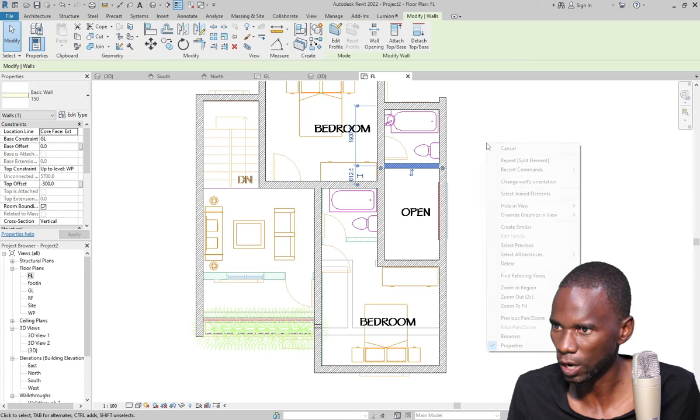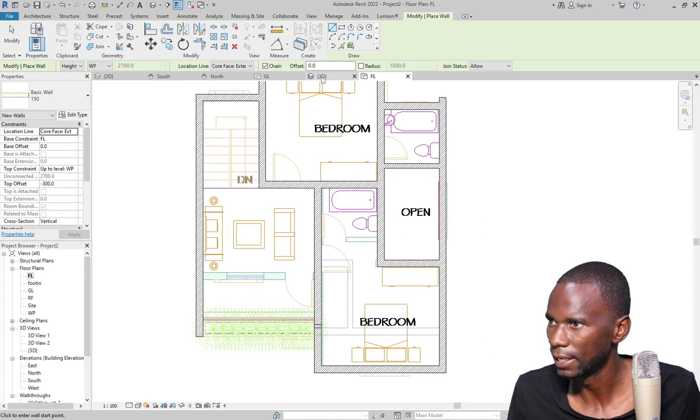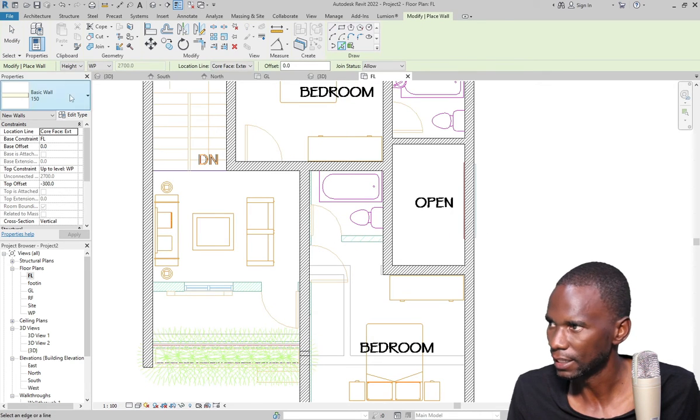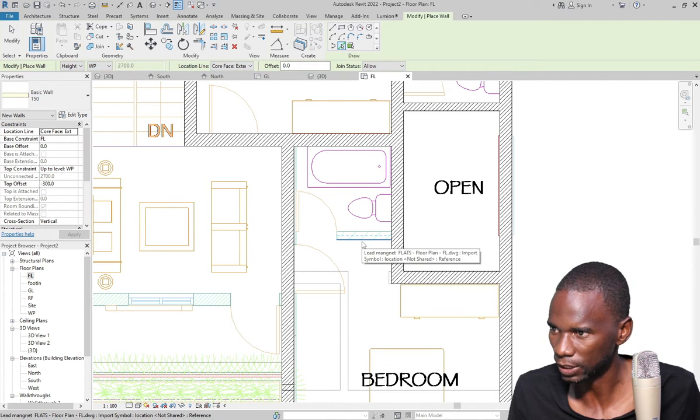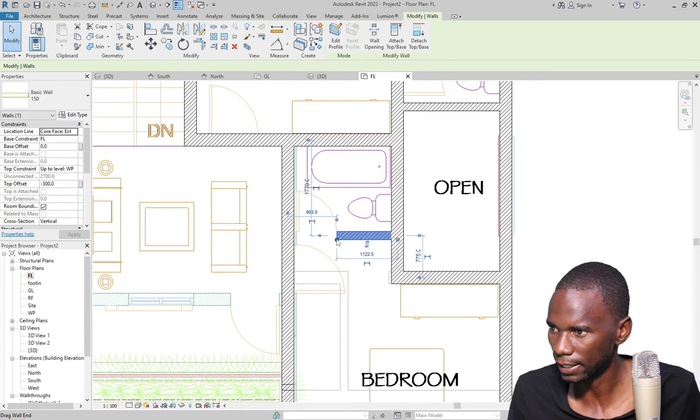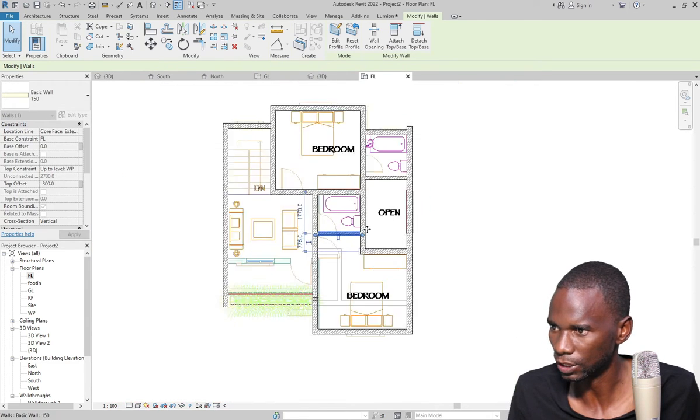So I'll just select on that one, right click, create similar, then pick lines, make sure that you check here, height, wall plate. So that's okay to start from this level, select and modify, select once again and simply drag it up to somewhere there.